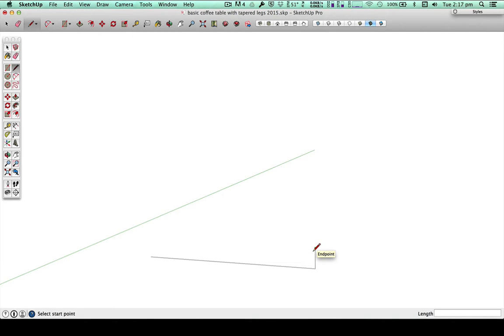There are a few other tricks as well, but it's very handy if you just roll over the line. If you want to draw a line that's exactly 65, because we do, we can simply roll over this line, and as we move back, there it is. There's a little dotted green line, and that's indicating that my red line is now at the same length as the line in front of it and ending on the green plane of the first line. So I'm going to click that, and might as well just keep going and close that.